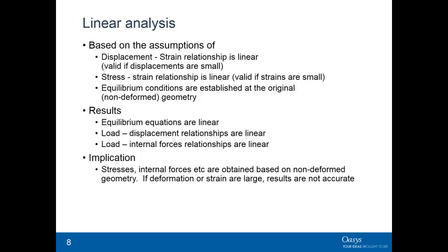And the thing to remember is that the results will be good if you've got small displacements and small strains. If you've got large displacements and large strains, your linear analysis results will not be accurate. You'll have results, but they won't be good results. And you need to spot this.